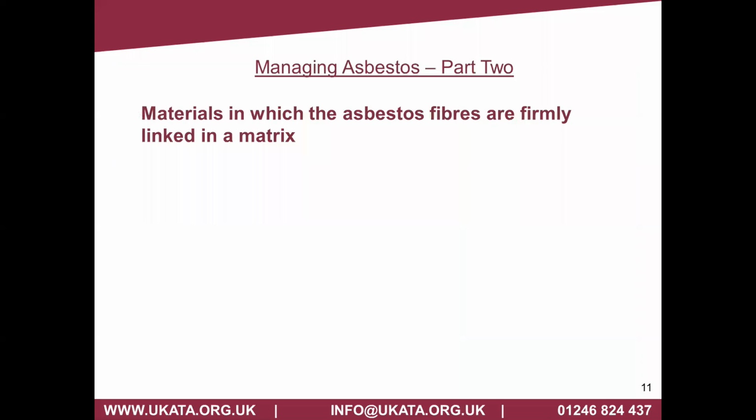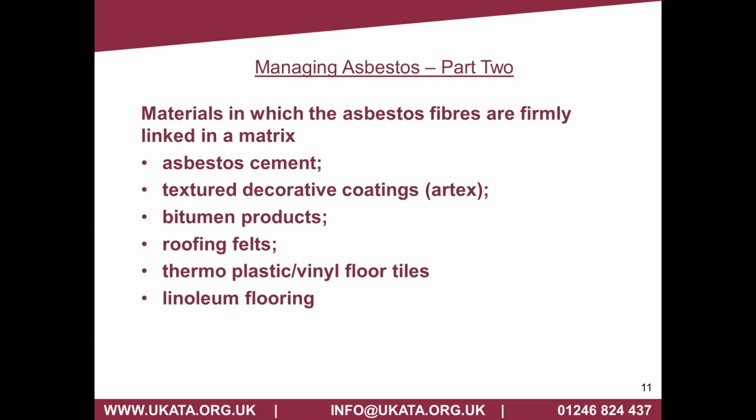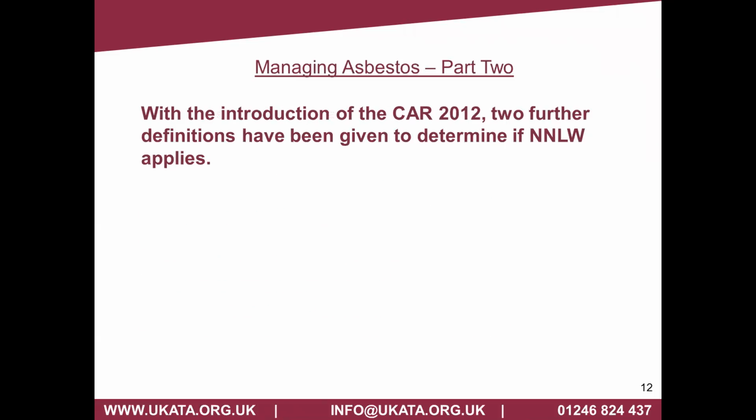Products which are classed as firmly linked within a matrix, so again, common products which we've just mentioned: asbestos cement, textured coatings, bitumen products such as roof felts and adhesives, thermoplastic and vinyl floor tiles, linoleum flooring, and then of course the old common toilet cisterns, hard black resin-based cisterns, which again lock the fibres in place.